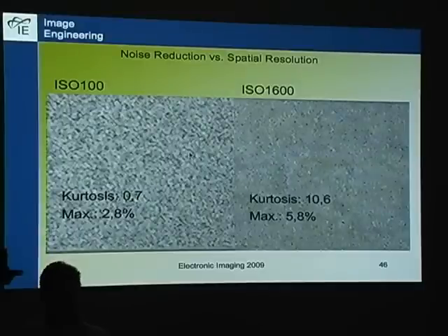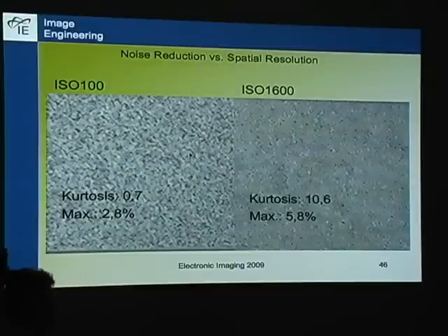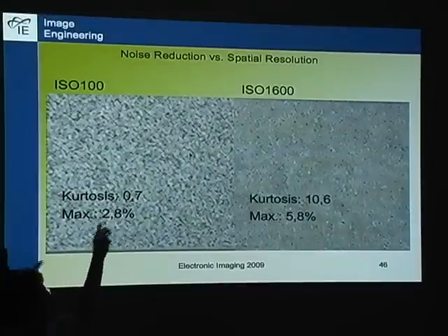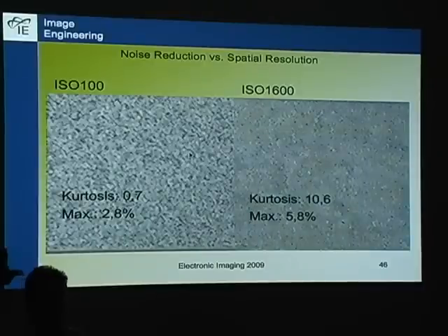And we've done this on a variety of different cameras now, and it seems to work pretty well. The only problem we have is, of course, depending on the algorithms that the manufacturers use, they are doing this noise cleaning from a certain contrast level on, and it's the trickiest thing here to select the correct contrast of the white noise to have this affected by the noise cleaning algorithm.